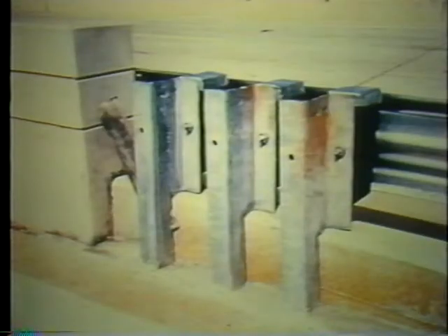One maintenance issue to pay attention to is post support, because adequate post support is absolutely critical. You see here a situation where the design did not fit, so half the flange and web were cut away to fit the post around the curb. At the transition to the rigid bridge rail, where post strength is needed most, there is now very little.